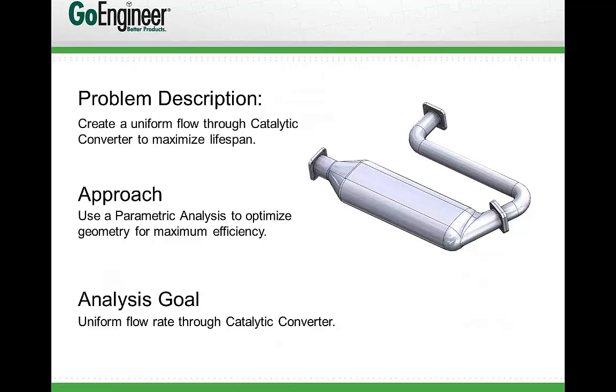We know that catalytic converters use very expensive metals. One of the goals of creating a really good catalytic converter is normalizing the airflow over all parts of the converter. So you're not getting one side with more airflow than the other, because it'll burn out one side versus the other, and then you essentially have to replace it before all of those very precious metals are utilized within the catalytic converter. Very expensive. So you want to really normalize that flow to maximize the lifespan.